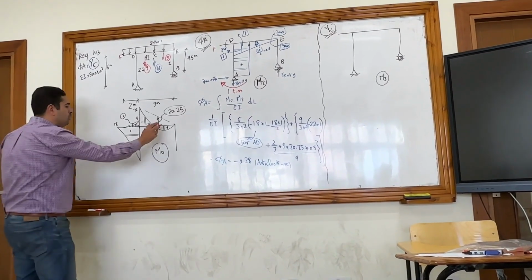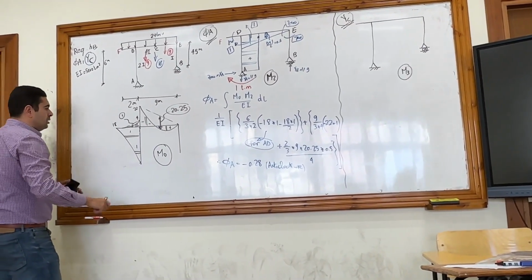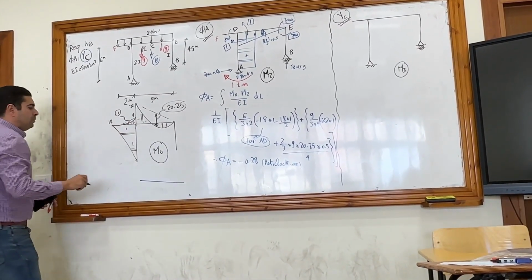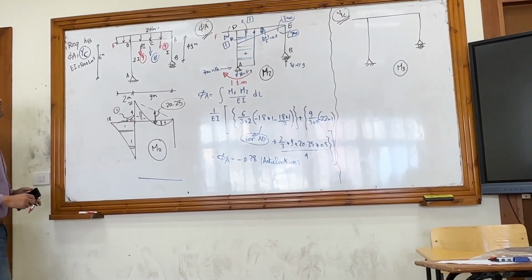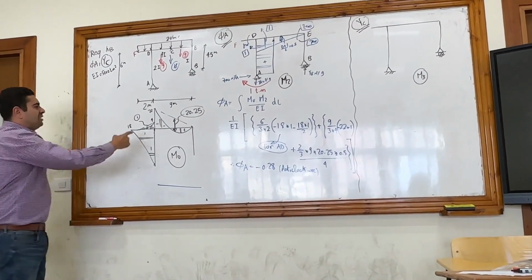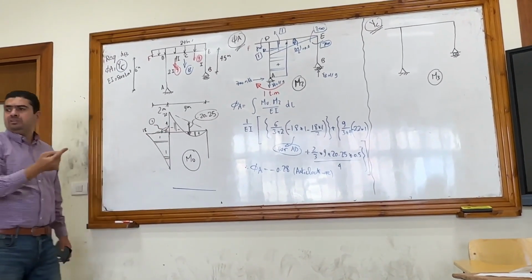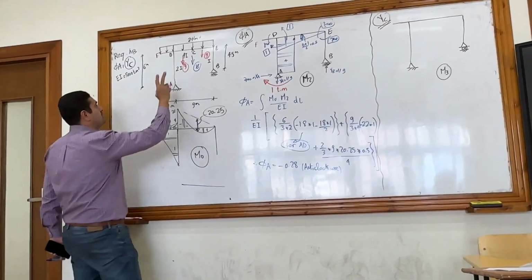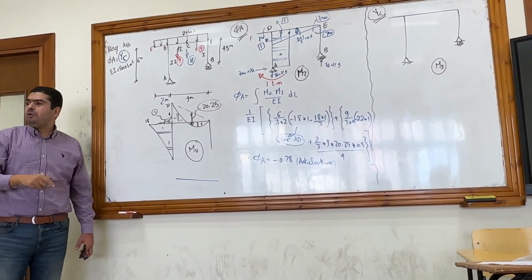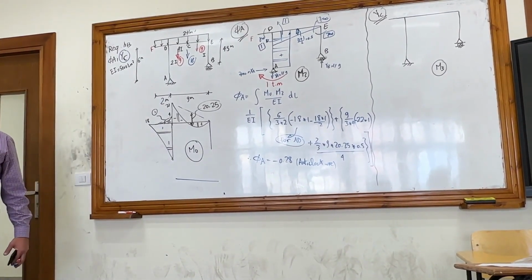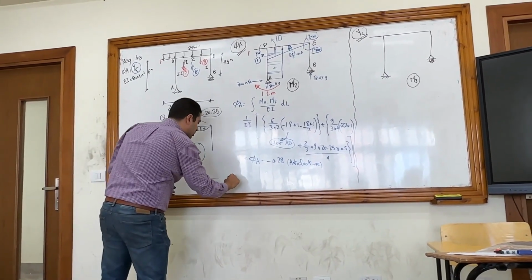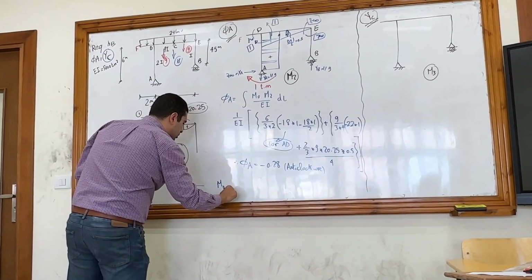Now I have to draw just the moment for the horizontal member that has a problem. How will I draw it again? So this can't be one curve. Now I have 2 distributed loads, DC and CE. So here in the M node modified, there will be 2 curves. Okay? So this is called M node modified.